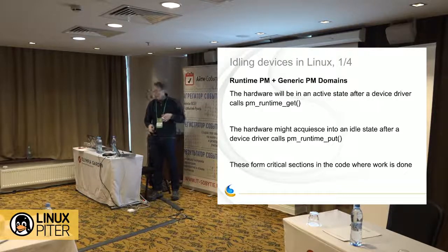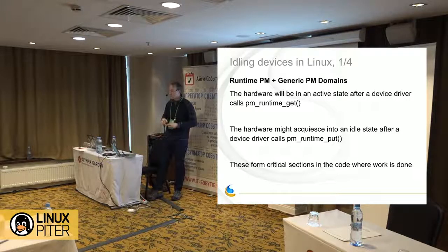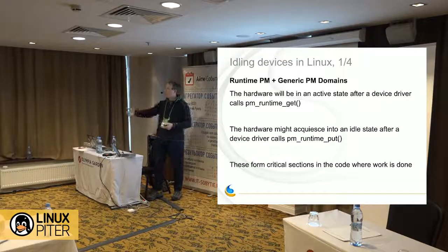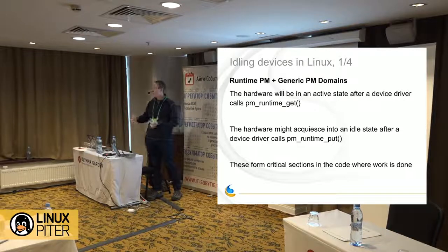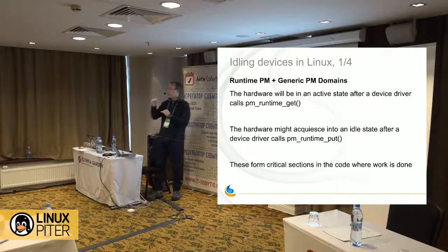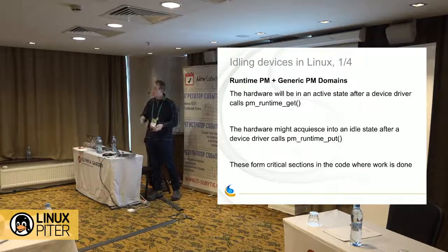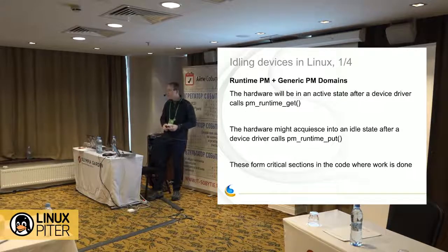Runtime PM is the interface to control the power state of the hardware for Linux device drivers. Before drivers do any work, they should call PM runtime get. And then when they're done doing work that involves the hardware, they should call PM runtime put. These two functions basically define a critical section in which we expect the power resources to be enabled. After you call PM runtime put, it's possible that the device will quiesce and hit a low power state. Of course, other device drivers may be using the same device, so you don't really know when it's going to happen. But the point is that that's the critical section of work.